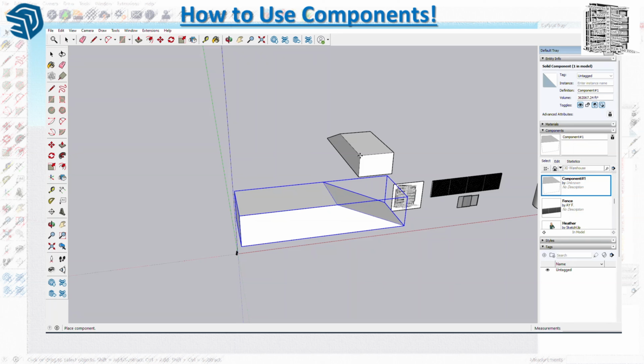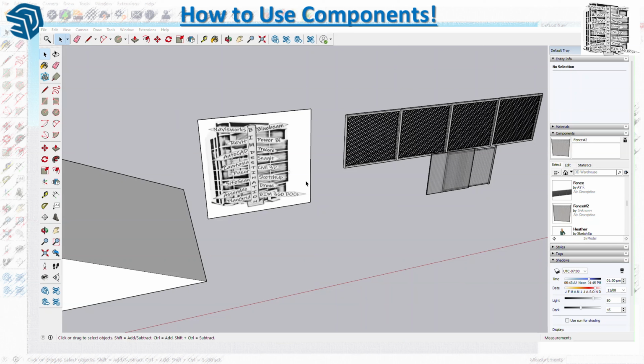So right now I want to give you a quick tip on how to set the axis and also how to align it and fix your thumbnail. Let me triple click my component. Right here I want to say glue to any surface, and I want to go to my set component. You can see the shadow under it. That tells me how this geometry is going to look when you grab it from your library. So I'm going to place this point over here.